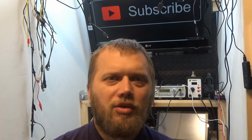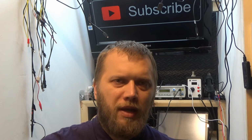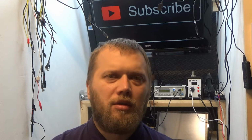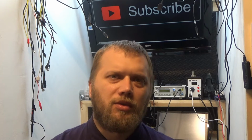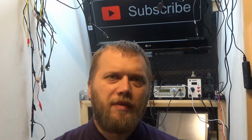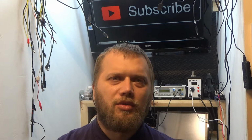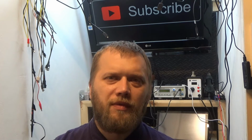That's why, and I will show you that in a moment, when you look at a symmetric square wave, the one that goes plus and minus the same value, the RMS of that signal would be the positive peak value of the signal. So if your square wave goes to plus and minus 2 volts, the RMS value is 2 volts. Now it gets a little bit more complex with other waveforms, like for example a sine wave. Because the sine wave is constantly changing, it is not that simple to calculate or just take a value, because a lot of it depends on the shape of the waveform and so on.